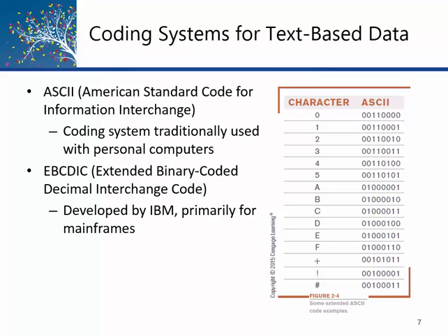This is the ASCII code standard for everything you see on your keyboard. ASCII is how you pronounce that. That stands for American Standard Code for Information Interchange. And the key there is information interchange. Two devices are going to interchange information between them because they're going to be speaking the same language, and even more specifically, they're going to be using the same standard code. So when a keyboard presses an A, the voltages it sends are 01000001, and every device that connects to that keyboard knows that that is the sequence, the byte of information that gets sent when a capital A is pressed.